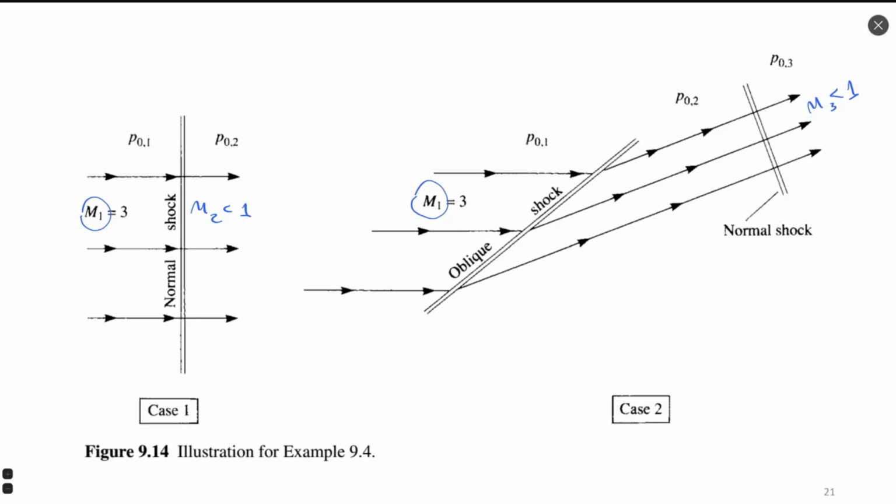So vehicles that fly with supersonic velocity have to have some device inside to decelerate flow in an efficient way inside the duct, to use this after inside the engine to burn fuel and to produce additional thrust. So the goal is this, to decelerate to subsonic velocity.